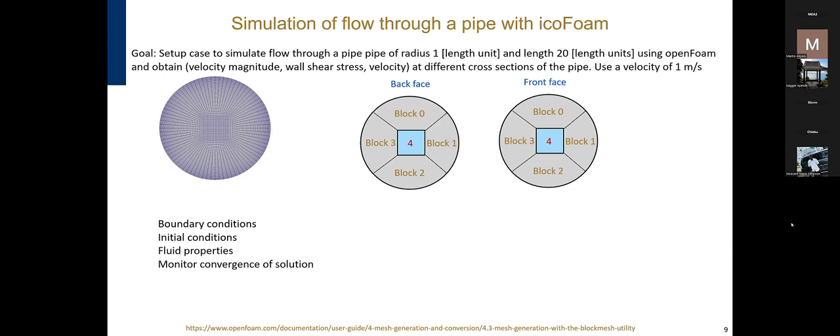It has to be equal to the velocity of the wall, which is not moving, so it's zero. If the wall was moving, then the fluid close to the wall would have to be equal to the velocity of the wall. So you need to take care of that. At the walls, you have the no slip condition. So we already have one condition there.